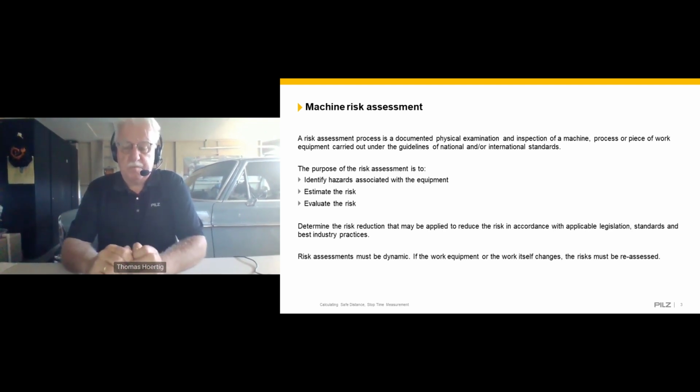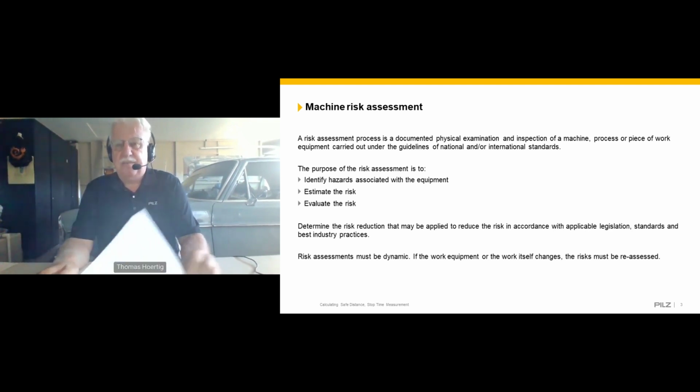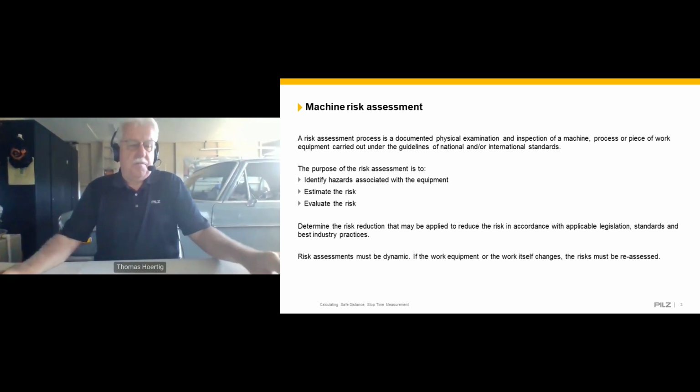So if your work equipment, the machine, or the work itself changes, the risk needs to be reassessed. Now, if your risk assessment would call out for a presence sensing device after you look at possible risk reduction, then the following presence sensing devices are available.